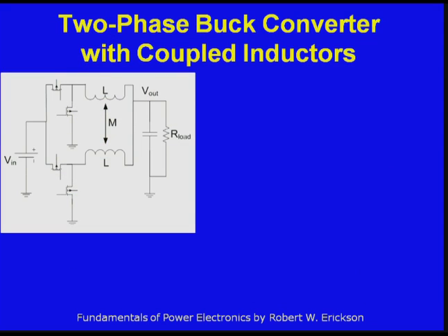Shown here is a buck converter, a basic circuit design. You saw some examples of other voltage converters earlier. This is a two-phase version. Basically, it's very simple. You have the input voltage coming in at some higher voltage, for example 3 volts. Then you have switches that switch it on and off through an inductor. Then you have a capacitor on the output to help smooth things out, and then your load is over here.